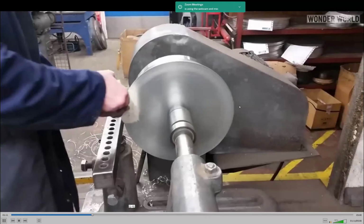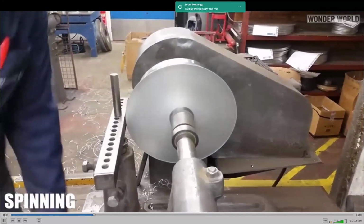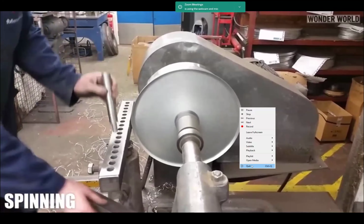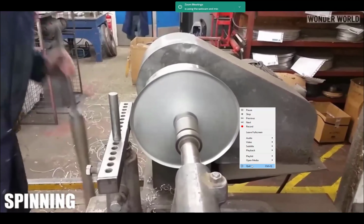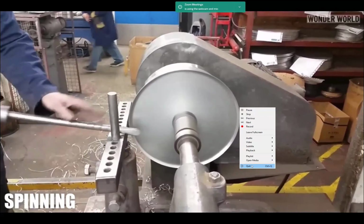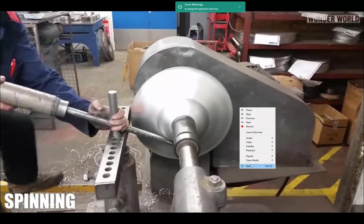Spinning works on a lathe. They attach a flat round blank onto a machine. While the blank is spinning at high speed, they use various types of tools to start pressing down the blank into the shape of a hemisphere. Once they've got 2 of them, they can weld them together to create a sphere. This method uses the skill of an artisan and a lot of labour to create the hemisphere.